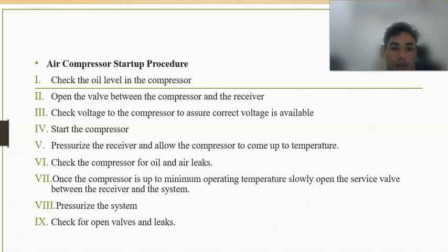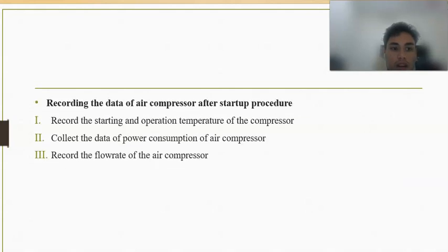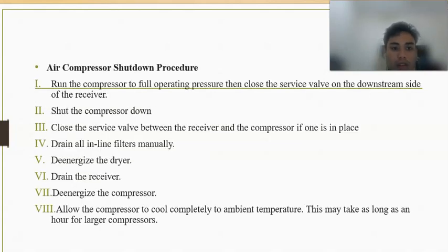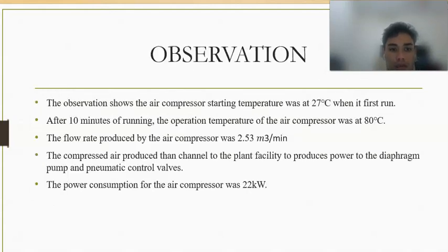There is a startup procedure of the compressor, and then recording the data of air compressor after startup procedure, where we record the starting and operation temperature of the compressor, and then the data for the power consumption, and lastly the flow rate of the air compressor itself. This is the air compressor shutdown procedure.